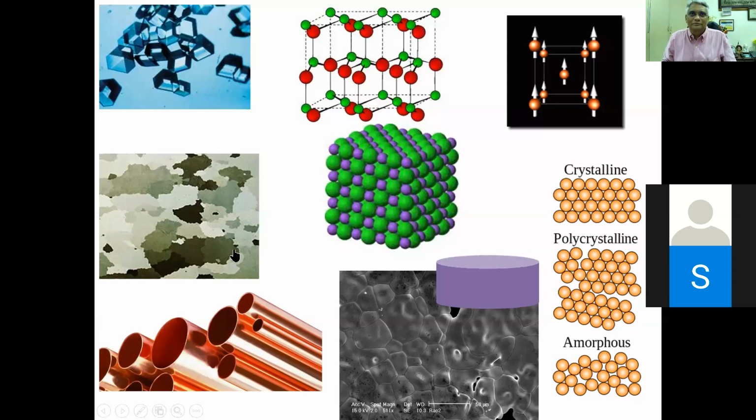So if you take a piece of metal, and especially in a place like Chennai, which is a humid place, okay. What happens? I mentioned this yesterday that grain boundaries are diffusion inlets and outlets also. So that means if this block is made of yttrium barium copper oxide, which is a superconducting system that I talked about, oxygen plays a very crucial role in addition to the stoichiometry of other cations. And if you get this in polycrystalline form, there could be out diffusion of oxygen from the lattice through these grain boundaries. That means what?